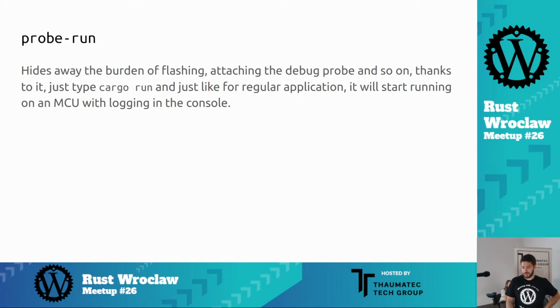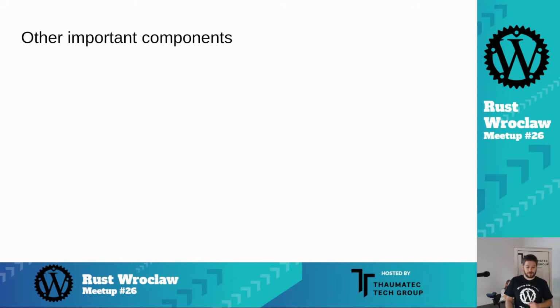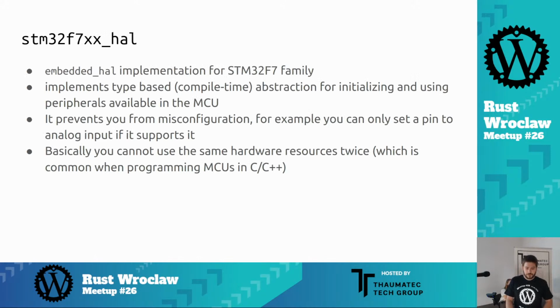So at the end, it makes the behavior of your cargo project look like you are developing on the host, like a regular Linux application or something like this, because you just type cargo run and it will flash the processor and it will start the application, give you the debug logs, and so on.